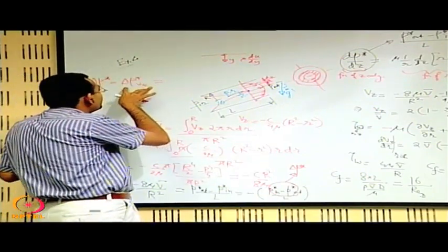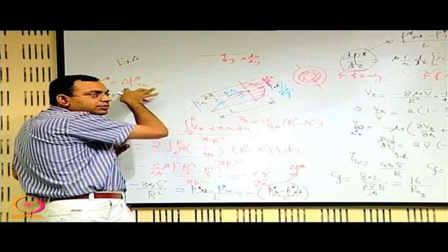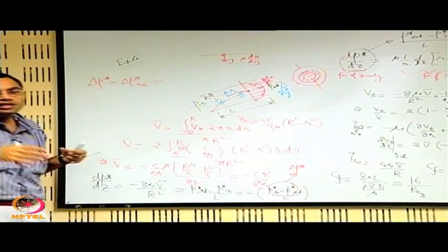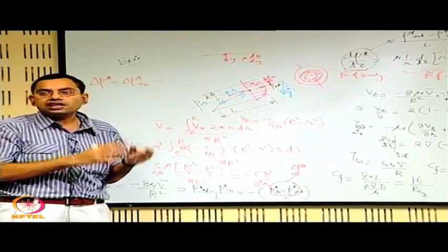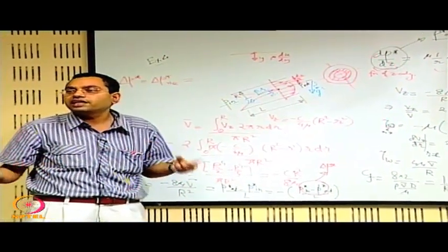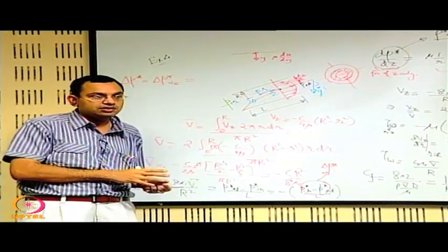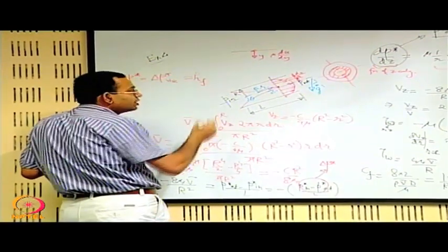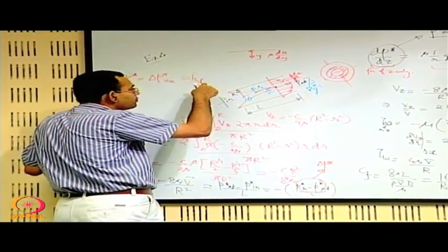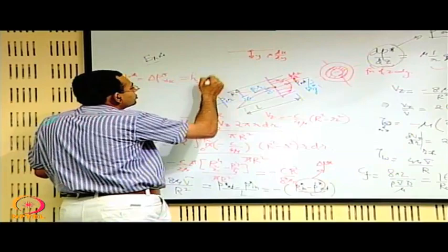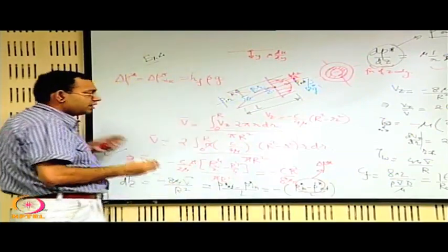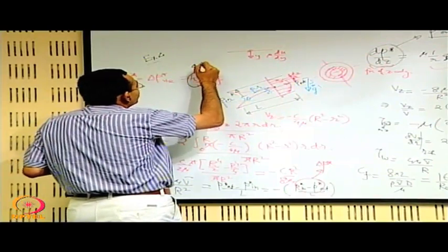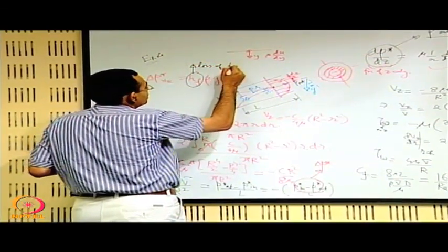We remember that pressure is some length unit into rho into g, and the length unit is the equivalent of pressure expressed in terms of length, which we call head, as we discussed earlier. If we write it in terms of a head with subscript hf, for friction, we can write hf rho g, where hf, as engineers, we understand is a loss of head due to fluid friction.